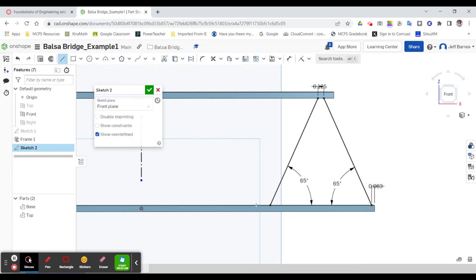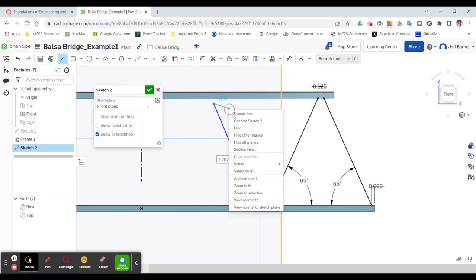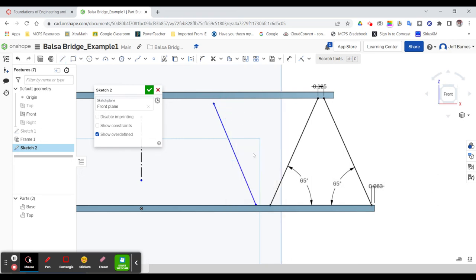Again, same thing. Kind of back up this direction. This is my pattern. If your pattern is different, then you're going to have a different design here. So if you were to have a vertical line in between these two, that's perfectly fine. You can have that vertical line there. But you would need to create a little more space in between, because then you'd have the thickness of this line, the thickness of this line, and the thickness of a vertical line, so all being 1/8 of an inch.